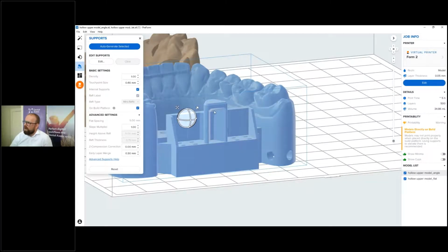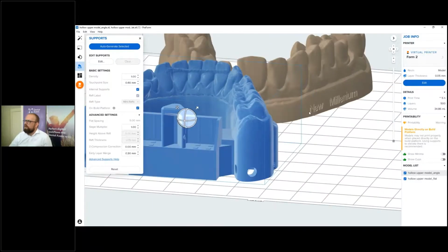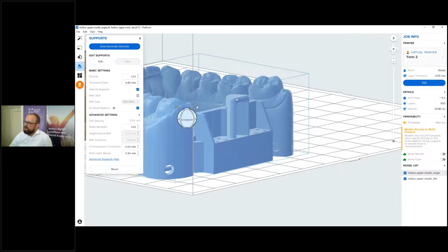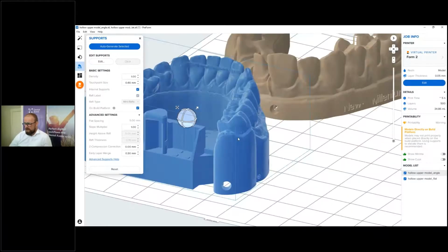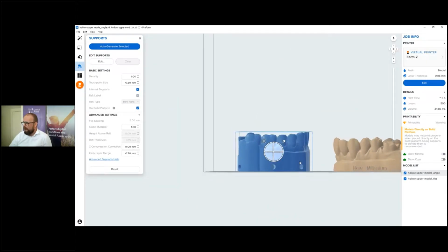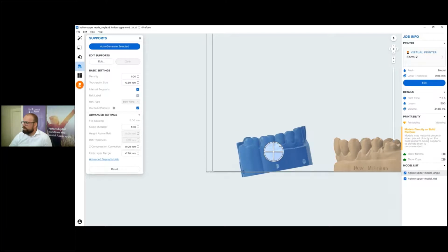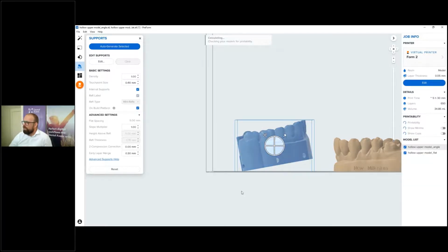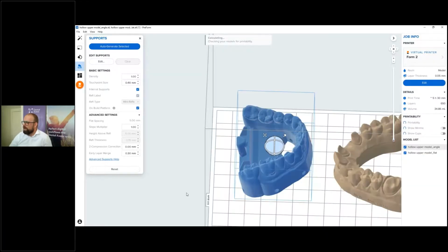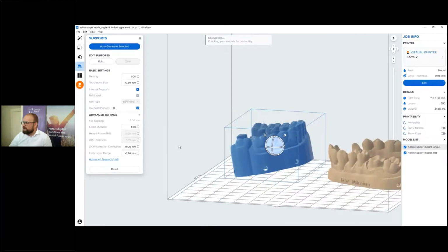There is a little angle over here. So if I tilt my model a little bit backwards, raising the incisors, this one becomes more flat. I need supports there. But because this is my connector for my articulator, I want as few connection supports as possible on that one. Still, it says the most amount of volume is closer to the build platform, that's still like this.